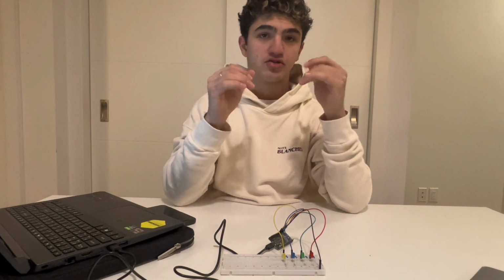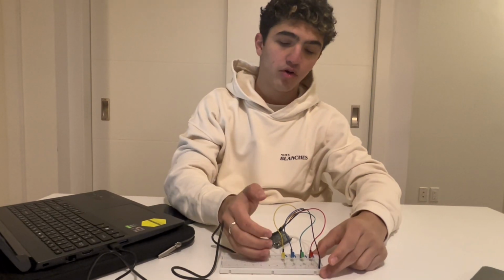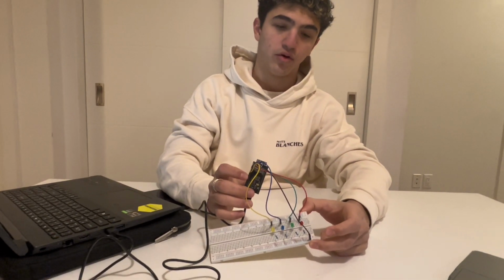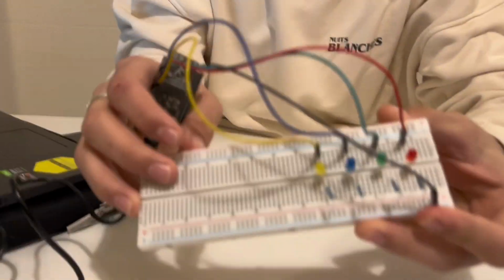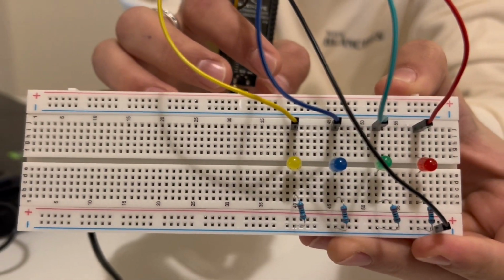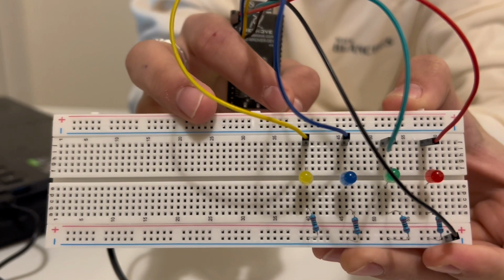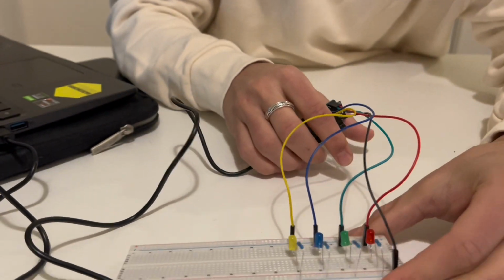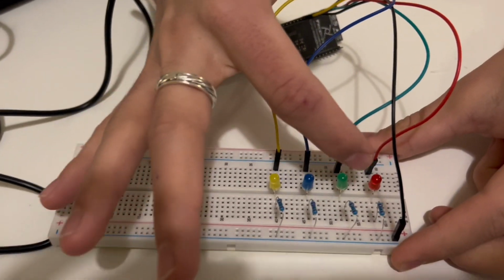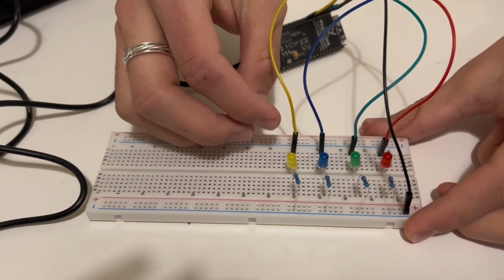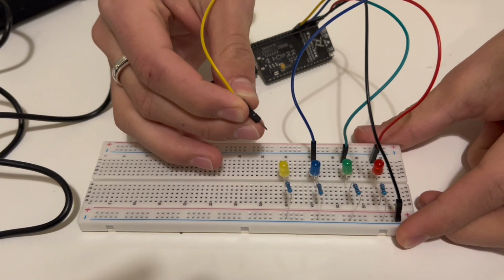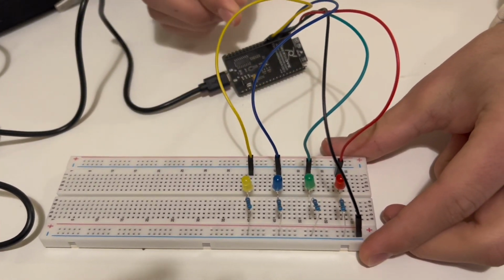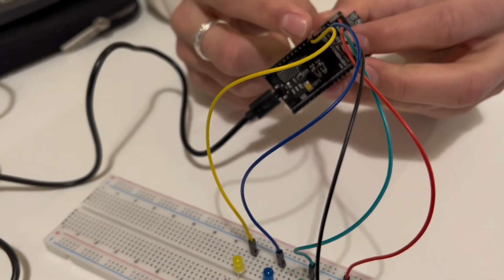In any of my Arduino projects, I like to start with step 1, setting up my breadboard with my ESP32 Arduino board. I would recommend you replicate this exact configuration, and you can pause the video right now and I will explain it in a second. Here we have 4 resistors, 4 LED lights, and the 4 male to female cables. You put the male side on the breadboard and the female side onto the ESP32.